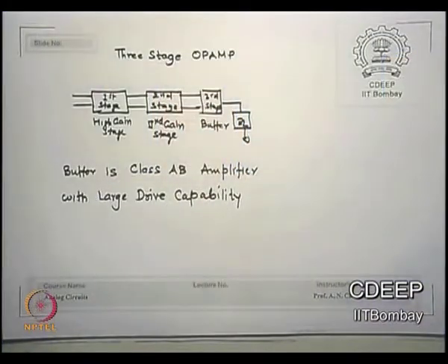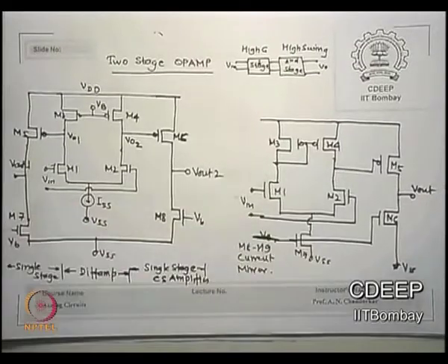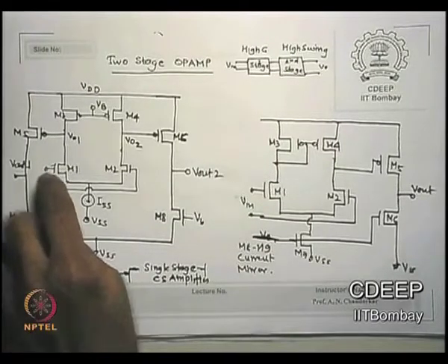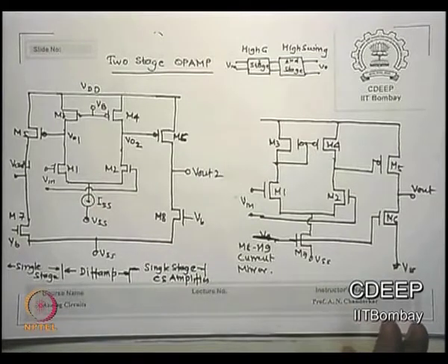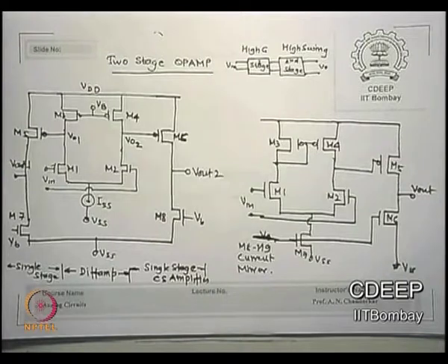However, if you look at the input resistance, can you tell me whether the input resistance of this OPAMP is higher or lower? Please look at it, there is a gate connection which is insulated from source and drain. So the input resistance of a MOS transistor is practically infinite, at least hundreds of mega ohms or at least tens of mega ohms and above. Is that clear? Let us say it is a bipolar transistor, will Ri still be higher? The base-emitter junction is connected there, so is it still higher? Yes, it will be relatively very high.